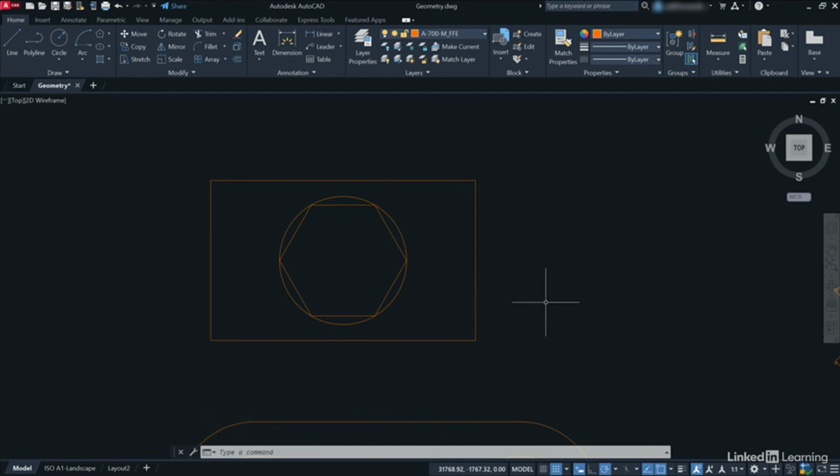Now, you might not want it inscribed within the circle. So let's just delete that particular polygon. I'm going to delete that now. I'll just hit the delete key on the keyboard to get rid of it. Now, you might get some weird things come up like that when you hover over the grips as well. If you do that, just move away, the menu disappears. We'll talk about grips and things in the AutoCAD Essential Training course that you do later, perhaps. So, with it selected, I can hit the delete key on the keyboard, or I could right-click and erase like we've done previously. I'm going to go back up to the polygon command here. There you go, polygon again on the little flyout menu.